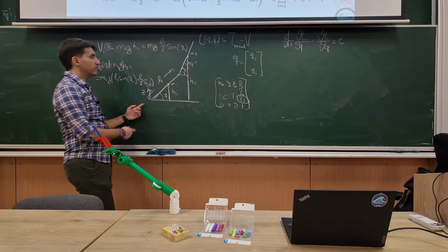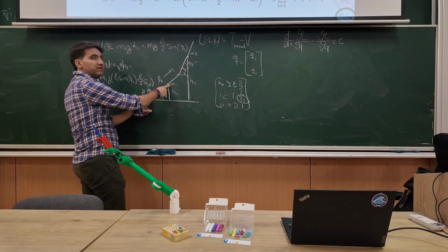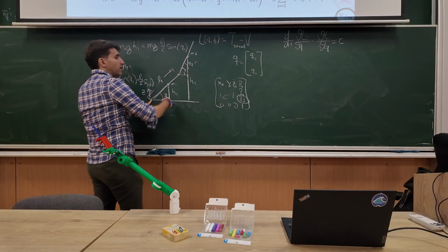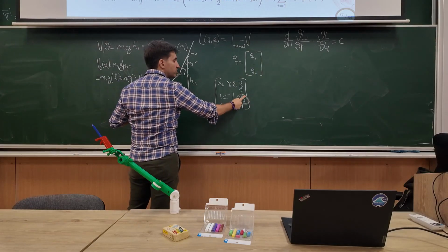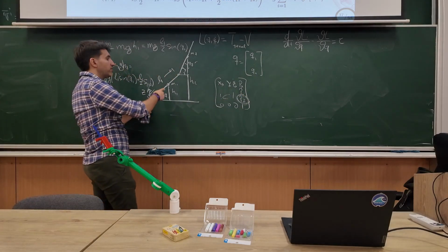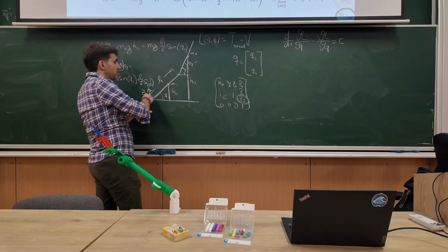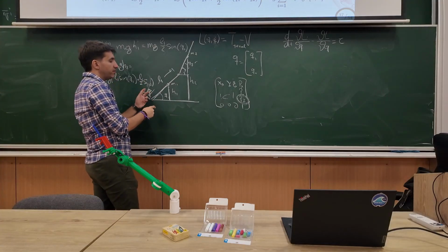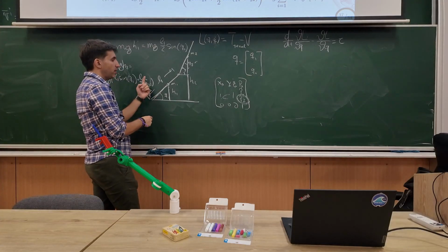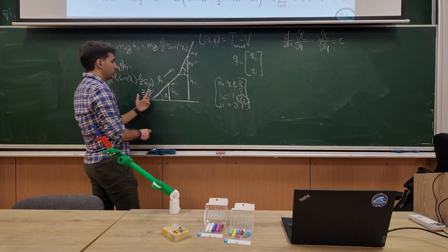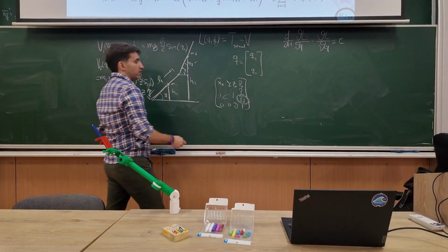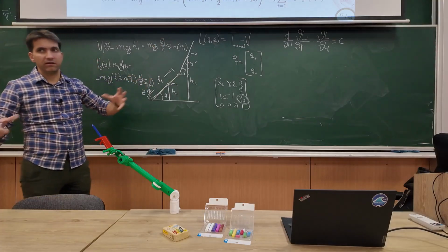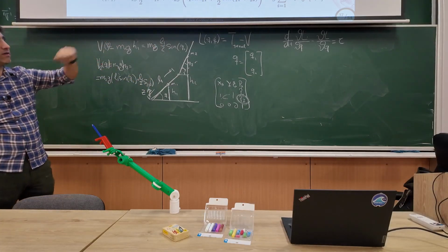So basically, by doing the forward kinematics until this mass, and until this mass, I can take the position of the coordinate frame attached here on the Z direction, or whatever direction is pointing upwards, negative to gravity. Yeah, I just thought of writing it in a more condensed form. That's the general way of calculating it, right?